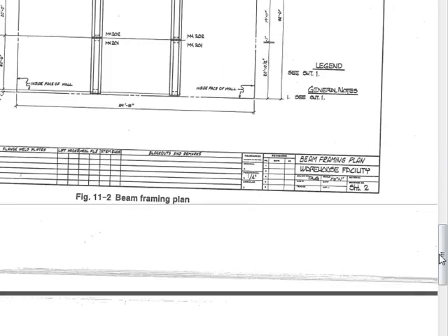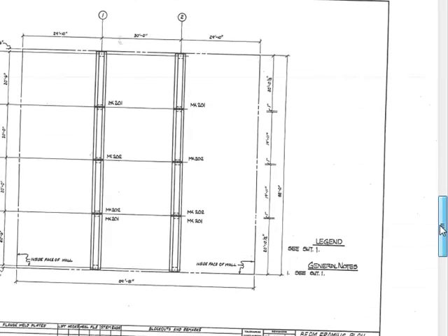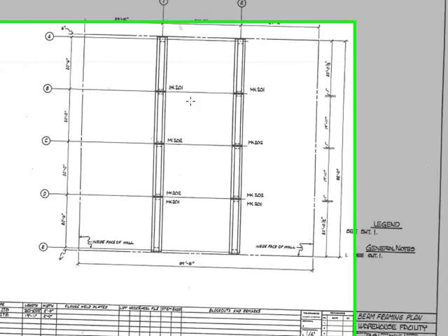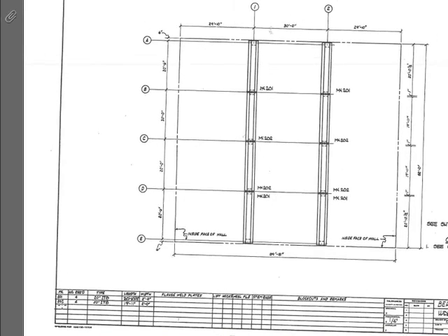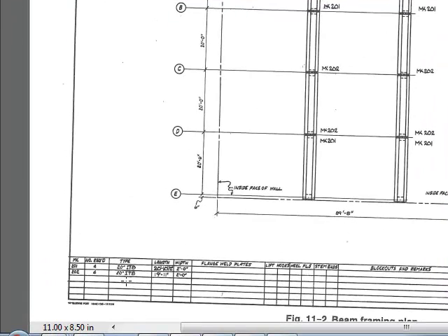Okay, this one here is the beam plan, and here you can see it's mark number 20, different numbers, but beams are in the 200s. So there's mark number 201, which you can barely read there, but there are 4 of them required. So there's 1, 2, 3, 4. They're the ones that are going to be at the ends. It's a 20-inch, looks like inverted T-beam, ITB, which you can go back to that other legend.